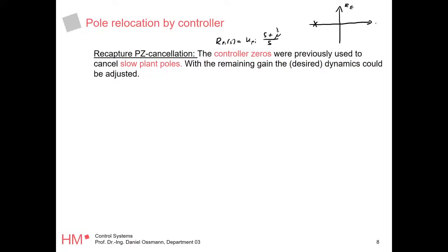For that system, you could say, I want to design a PI controller. I place my zero here above this pole, and I'm introducing a new pole. So this is the open loop. What you see here in red and black is R(s) times G(s), the open loop controller and plant.